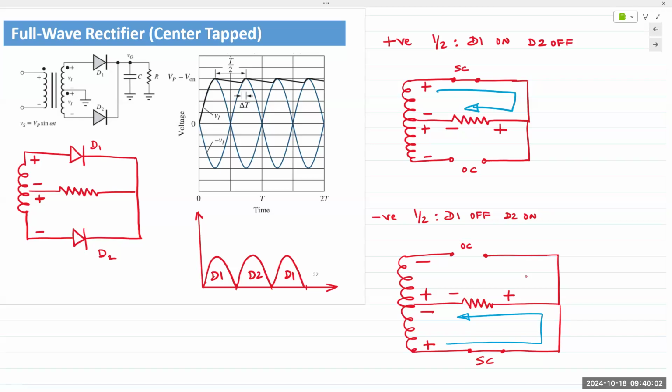That comes later, afterward, on top of the rectification. So the question being asked is about the capacitor and the filtering, and that comes afterwards. But the rectifier as it is, just with 2 diodes, this is the output we would obtain. Just 2 peaks. And now, because we're rectifying both halves, the average value of the waveform has risen. It's now doubled, right? Compared to half-wave rectification.